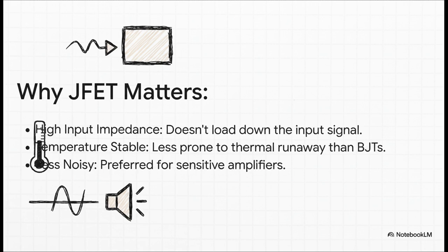That high input impedance makes it perfect for amplifying very weak signals without messing them up. They're also generally more stable when the temperature changes, and they're just quieter. They produce less electrical noise, which is why you find them in high-end audio equipment and sensitive scientific instruments.